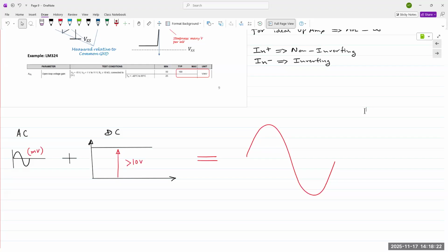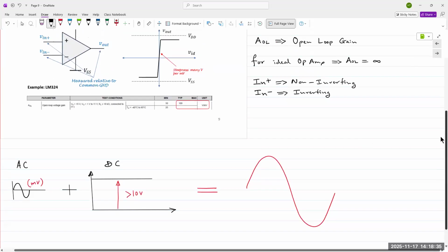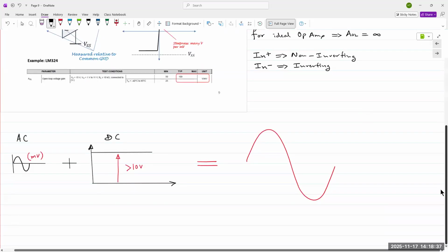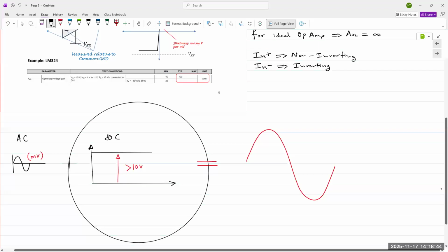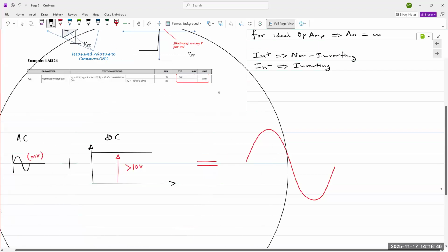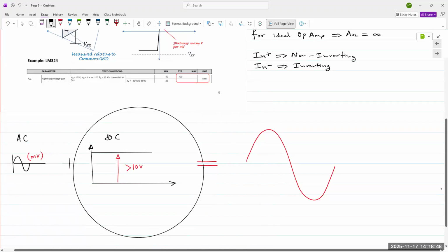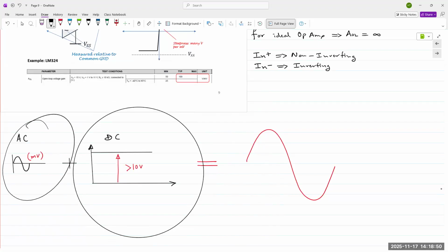Not really, because the energy to amplify a signal does not come from thin air. It comes from the DC power supplies that are connected to power that system. And so, in the most generic of terms, I always like to state an amplifier takes the energy of a DC signal and gives it the shape of the AC input signal.